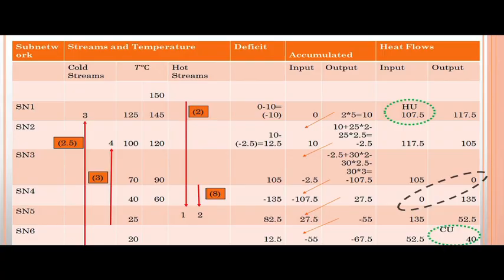Welcome back. We were discussing heat exchanger network analysis. We are halfway through. We have taken an example from the paper of Linnhoff and Hindmarsh, and the example discussed in the same paper we have picked up. So far, if we go a little bit back, this is the problem table. By tabular solution we have found the hot utility requirement, the cold utility requirement and the pinch point.